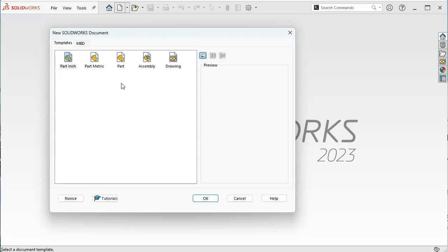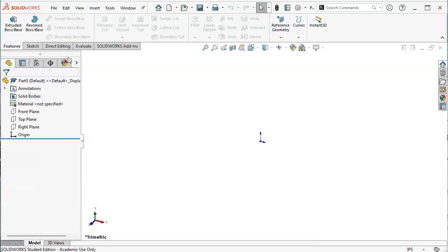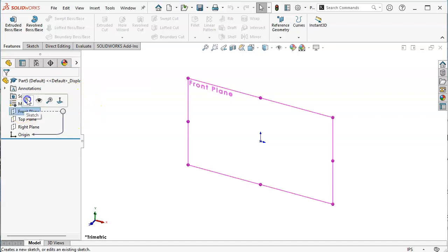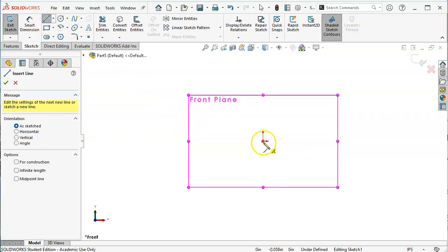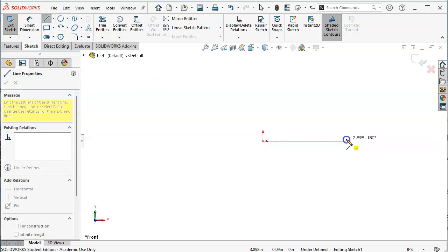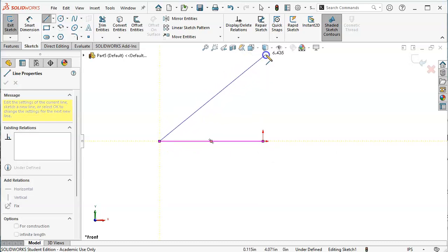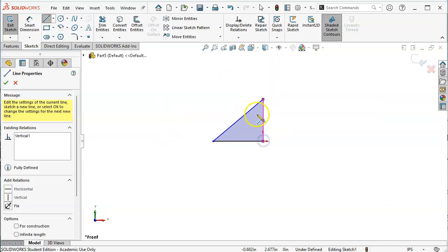again, might think about using the hole wizard for our pieces through the mounting holes, the 0.78, so that at some point, if we need to make those threaded or countersunk or do something different with it, that we would have that as an option in our geometry. So the triangle, and let's see, that corner, let's go this way so that when I use the fillets to knock those corners off,